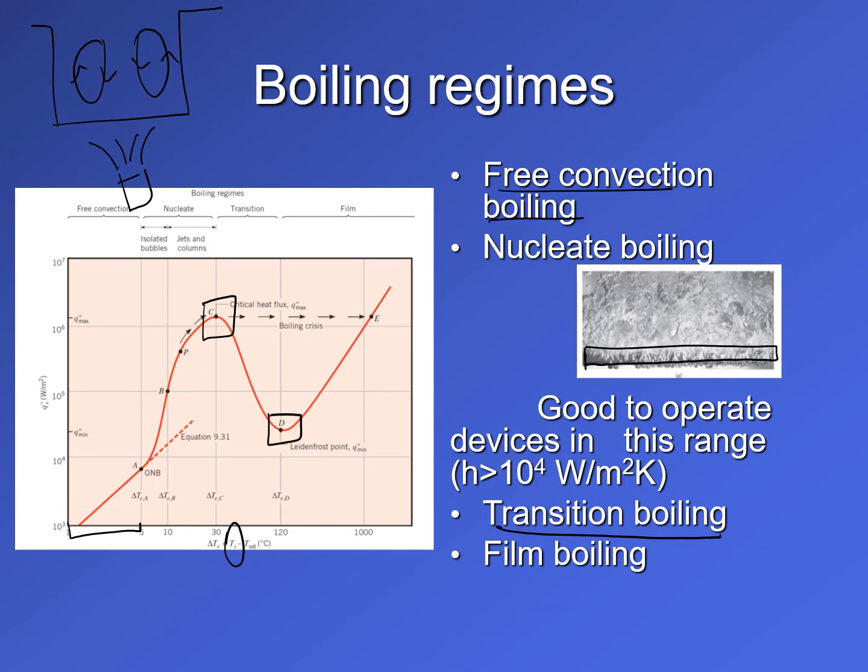So there is a transition between nucleate boiling, which is characterized by vigorous mixing above the surface because of the bubble formation, and a film that forms on the surface. This film provides resistance to the flow of energy, the flow of heat. As we know, the vapor has a conduction resistance which is much larger than the resistance to conduction for liquid. So this film blanket that starts to form on the surface with increased surface temperature results in a decrease in surface heat flux. That's the reason the curve starts to drop.